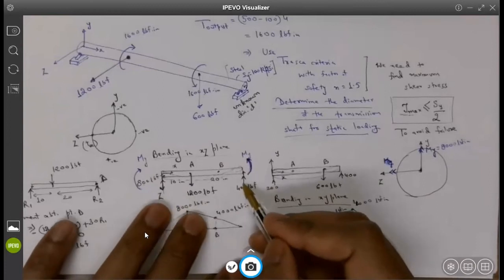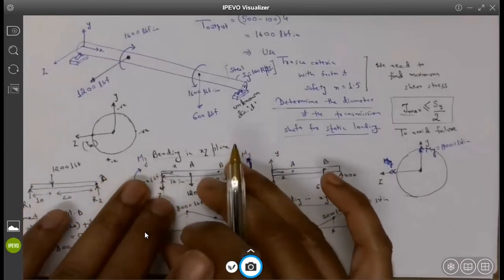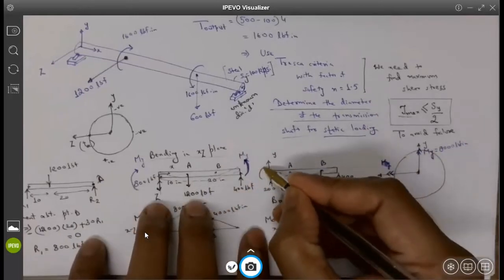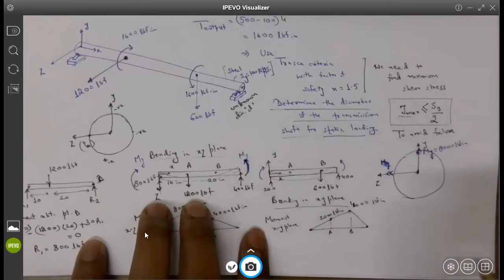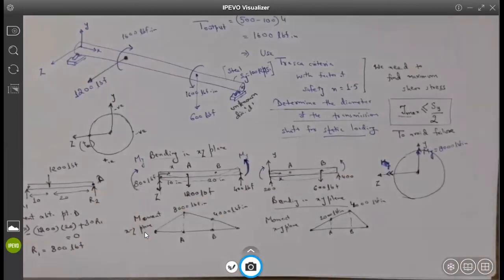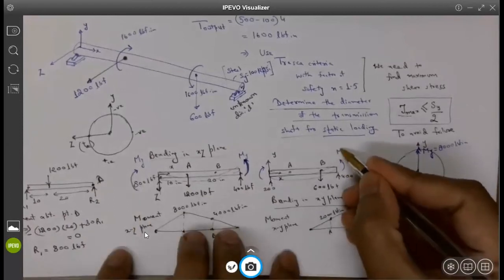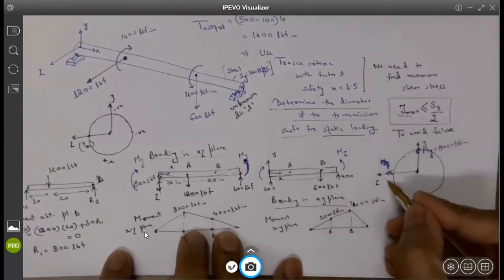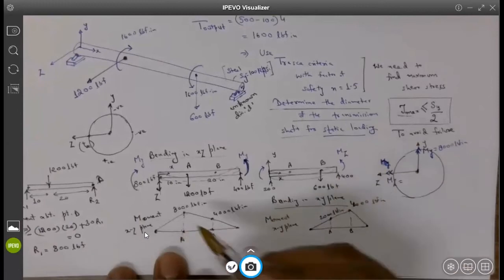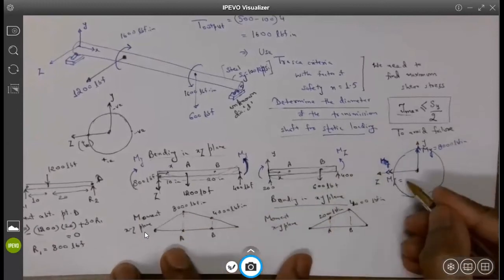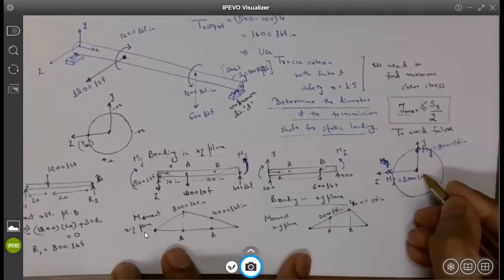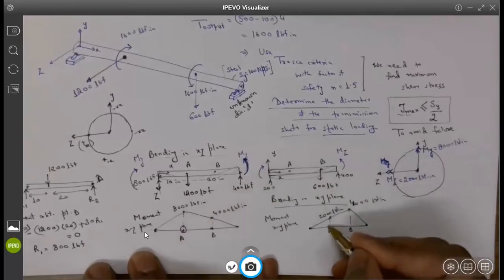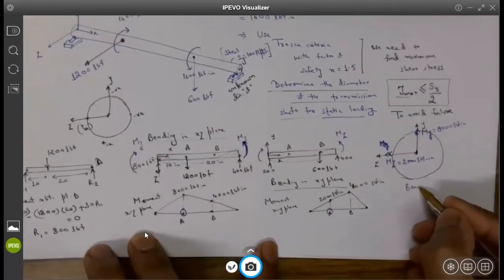Now, if you guys agree with me, or let's say you somehow followed this, can you help me to find the bending moment direction for this? It's in the Z. It will be what? M Z. And this is your Mz. And the value at this point is given by 2,000 pound force inch. We are looking at point A. This is the bending moment representation at point A.